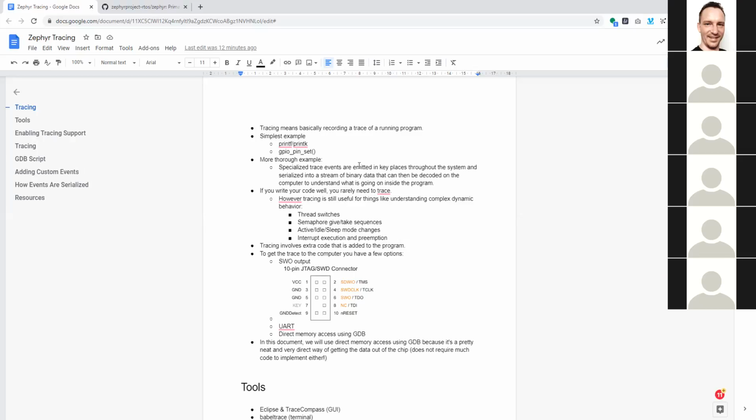The second common method is that you toggle a GPIO pin, and this is very useful because in some cases you don't actually have a timing budget to do tracing, as we're going to discuss today. So you're kind of forced to use those simpler methods of tracing the application. One such method is to simply toggle a GPIO pin or several pins and inspect the output signal with an oscilloscope. You can connect different channels of the oscilloscope to the different pins, and then toggle those pins at certain points in the application.